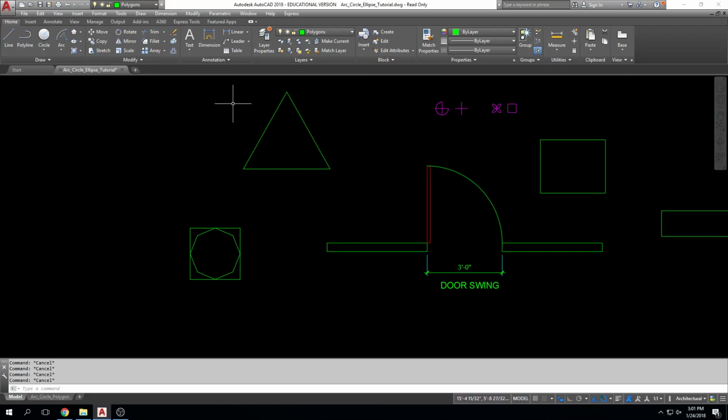All right. So we've created a few polygons, right? You can see it's very custom. I can create any type of polygon I want. So I click on polygon. Really the key to this is determining the number of sides, whether it's circumscribed or inscribed, which, unless you have a clear definition, for me it doesn't really matter that much, right? And then executing it with a dimension you input, right? 2 foot, enter, or touching another object, snapping to another object and getting that kind of graphic dimension.